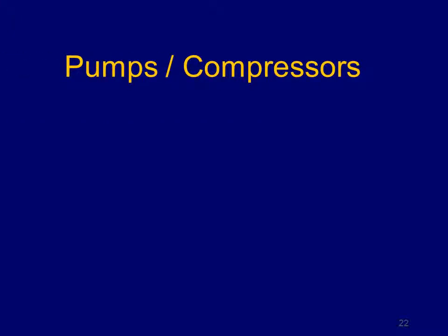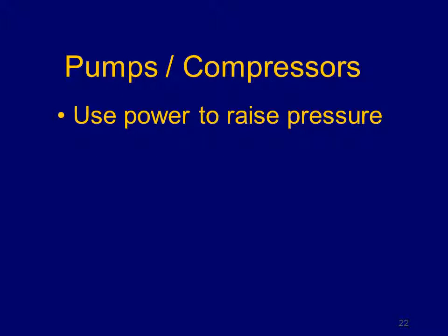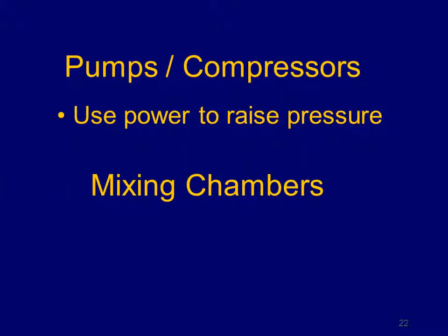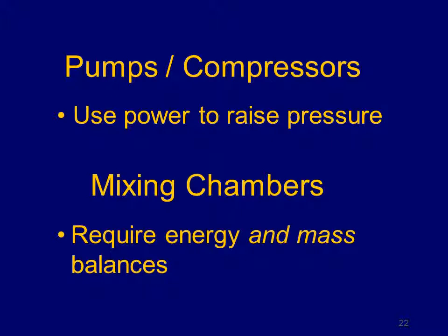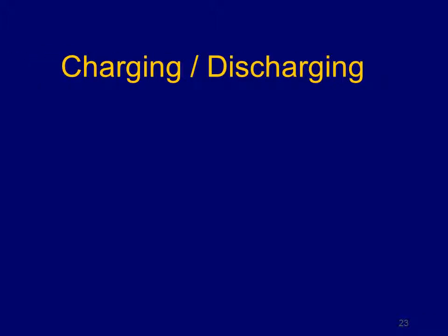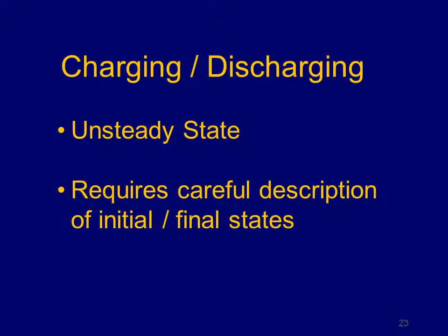Okay, we looked at pumps and compressors, where we use power to raise the pressure. We looked at mixing chambers, where we have to do an energy balance and a mass balance, fairly simple mass balance. And we looked at charging, discharging problems. I think of these as unsteady states, so we're combining really a flowing system with a system that's accumulating mass, and that gets to be a little tricky. So these problems require, I would say, careful description of your initial and your final states, and attention to detail in finding when you have to use, for instance, internal energy as opposed to when you use enthalpy.